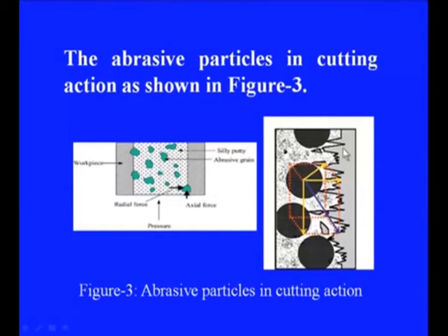So, this is a magnified view of the workpiece surface, where these are some of the roughness peaks, asperities, and these need to be smoothened out or cut, so that we can get a very smooth workpiece surface. This can be done with the help of tiny abrasive particles like this. These abrasive particles are pushed through with the help of this medium, which is pushed under pressure. While coming in contact with these asperities, some of these asperities get cut.